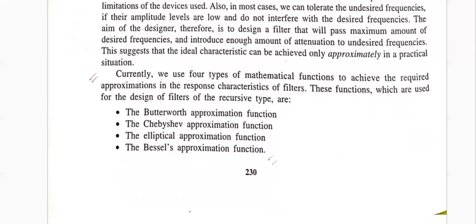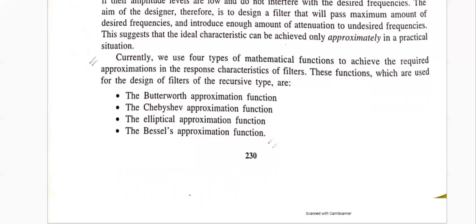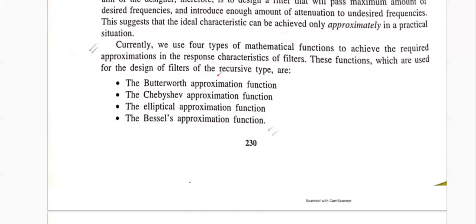So currently we use 4 types of mathematical function to achieve the required approximation in the response characteristics of a filter. These functions are used for the design of filters of the recursive type. Recursive means we need the feedback. They are the Butterworth approximation, Chebyshev approximation, elliptical approximation, and Bessel's approximation.